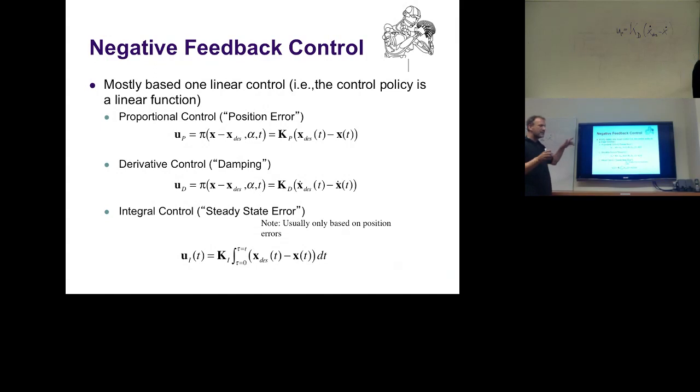This is actually important: if you get pushed to the goal, you may start oscillating around it. And if you want to be stationary at the goal, you penalize for the movement, that means you want to have zero desired velocity, then you will come to a stop. So that kind of damping is critically important to dampen the movement out of the system to come to a full stop.